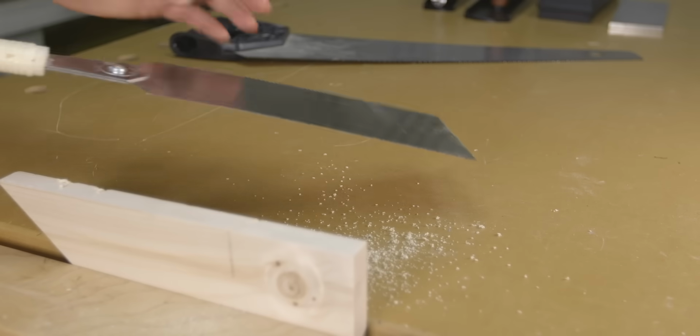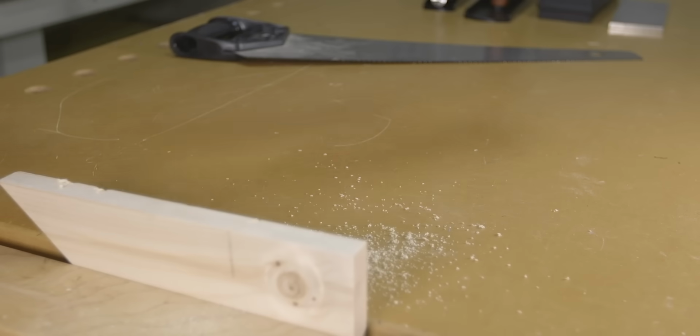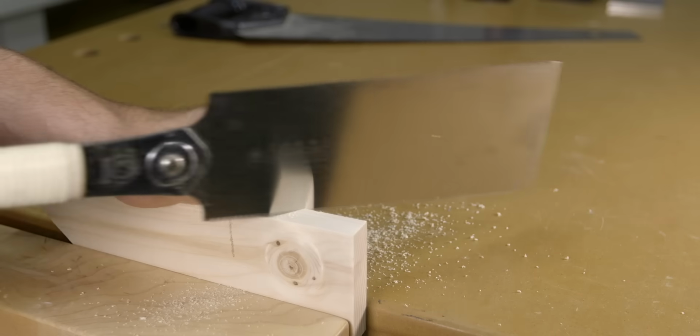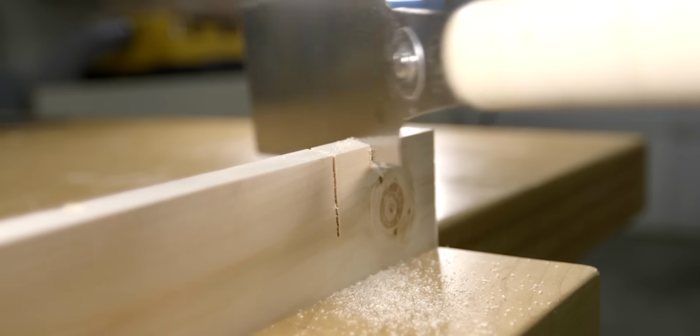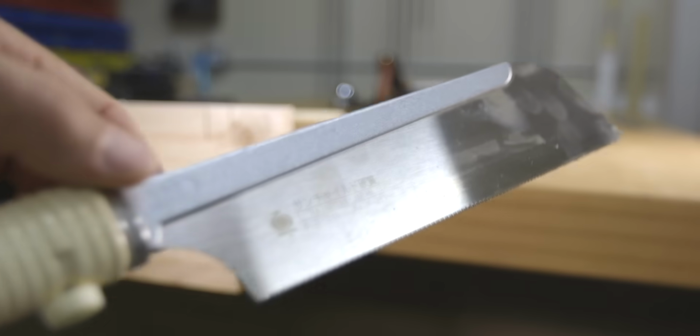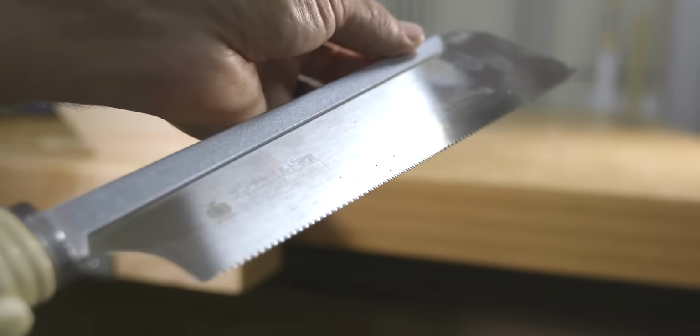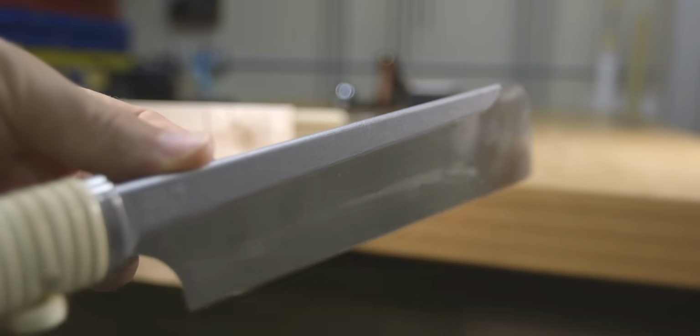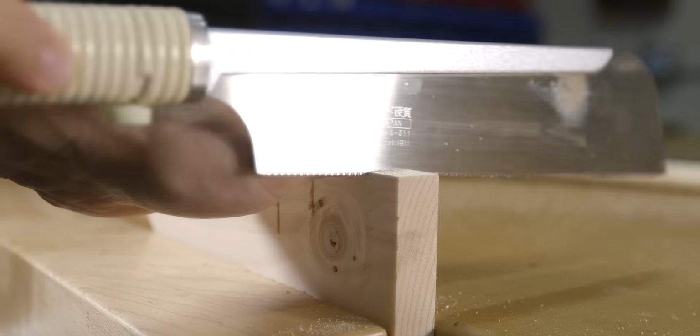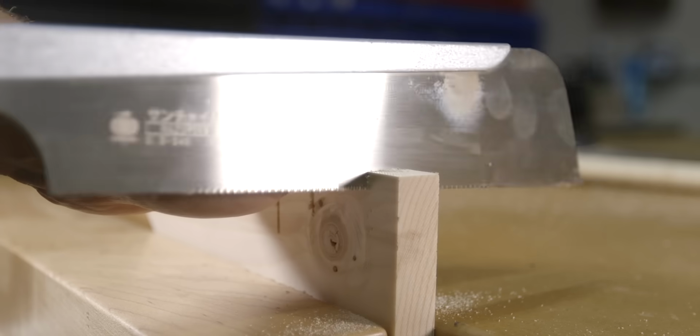Next are pull saws, also known as Japanese saws. They are absolutely fantastic saws. Great for control, flexibility, and require less effort because they cut on the pull stroke. The last saw to look at is the back saw. The back saw, again, is a general term. It's used to describe any saw that has a stiffened rib along the back of the saw. This rib greatly reduces any flexing that the blade may encounter while in use, because the less flex, the straighter the cut.